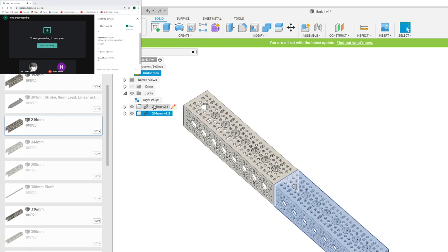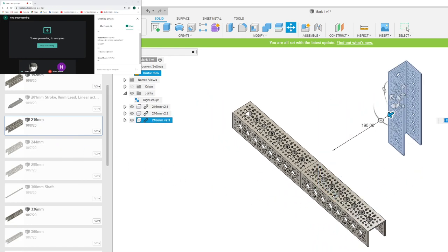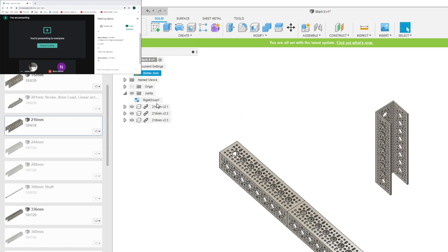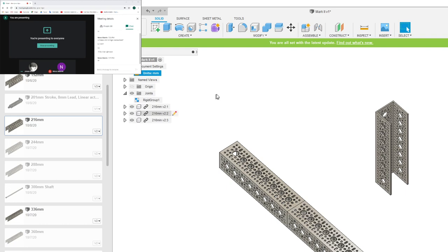You can select things, but it'll change what you select. You can hit Control to select individual things, so I could select this in the rigid group. It only works within these different things, so I can't select this how I would. Let me just hold up. Let me insert this piece just to show you how Shift works, because you need more than one. So I can have Control to select individual pieces, but keep my other ones. And then Shift basically makes a selection list.